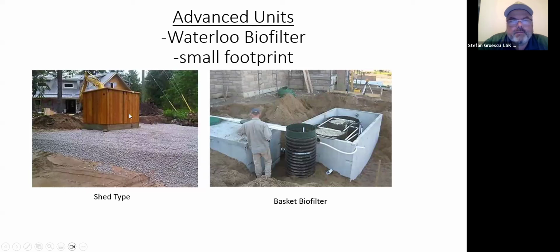So basically what happens is from the septic tank, the effluent is sprayed onto the foam blocks or sponges. And it's a sponge, so there's a lot of air in it. So that's where the bacteria treats the effluent. So you can see now that the treatment of the effluent is done prior to releasing it back down into the ground.